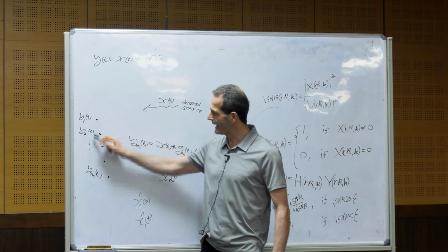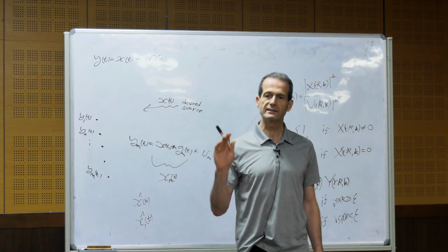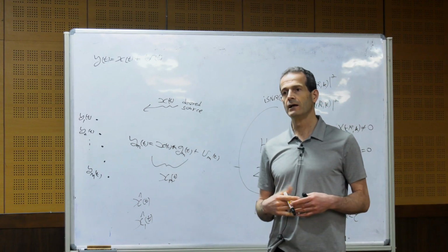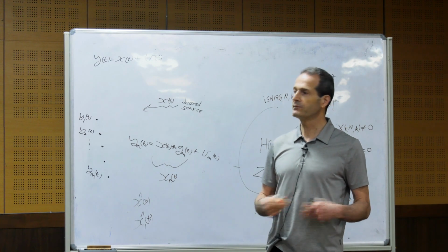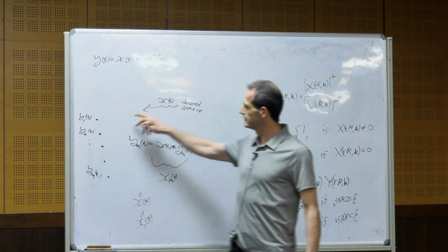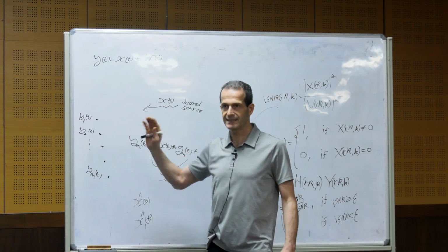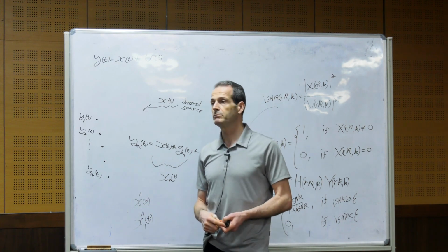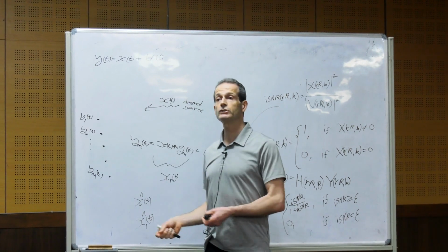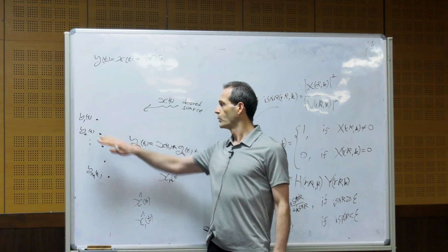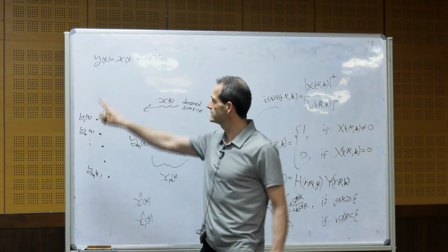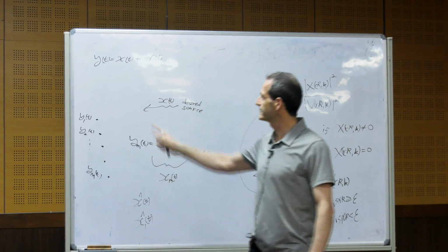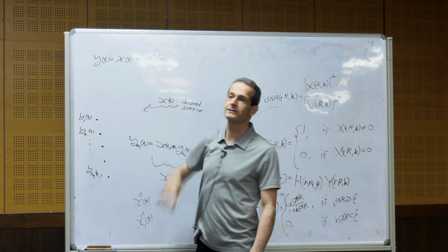Because out of M sensors, I need to choose one of the sensors, and I call it the reference sensor. It means that for me, if I didn't have noise, the signal that was measured in that sensor maybe has less reverberation, maybe it has a higher signal to noise ratio. So I start with one of the sensors. You see, with a single sensor, I cannot choose a reference sensor because I have only one. So I take this sensor, I try to suppress the noise.